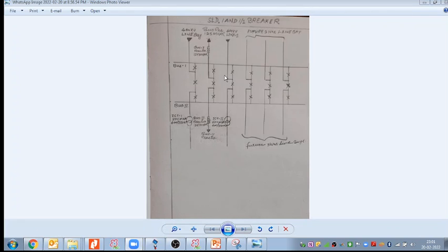Line bay two. See, both line bays together again. That is the bus reactor. Please put the bus reactor along with the ICT. How to arrange the feeders, that is also one skill. I will explain how to arrange the feeders during the SLD. Line here, all the lines together and all the ICTs together.